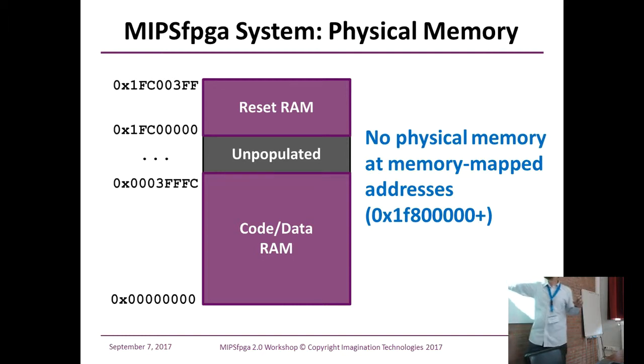The addresses in the middle are all empty. If you read and write from these addresses, if there's nothing, it should cause an address exception for MIPS. This is what we call an I/O hole in industry terminology. This gap in the memory map is generally used by input-output peripherals in memory mapped I/O.